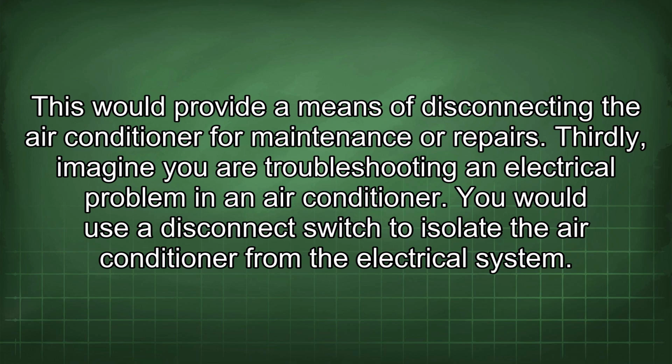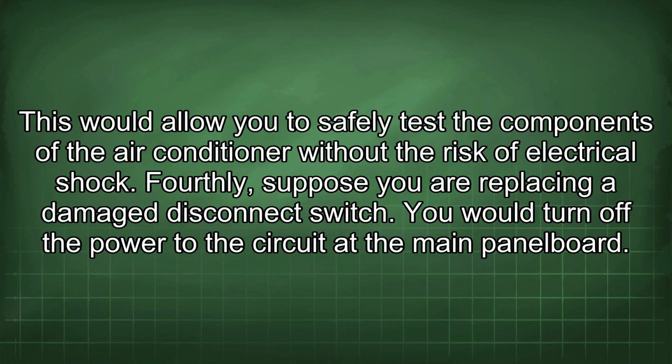Thirdly, imagine you are troubleshooting an electrical problem in an air conditioner. You would use a disconnect switch to isolate the air conditioner from the electrical system. This would allow you to safely test the components of the air conditioner without the risk of electrical shock.